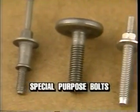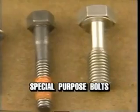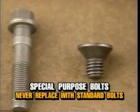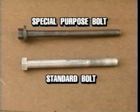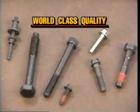Most bolts used in automotive engines are designed for a specific application. These bolts can vary in shank size, head size, thread pattern, and use an integral washer. Never replace these bolts with standard bolts. The features of the special purpose fastener allow it to meet the needs of a specific application. These bolts may not have a grade stamped in the head like standard bolts.